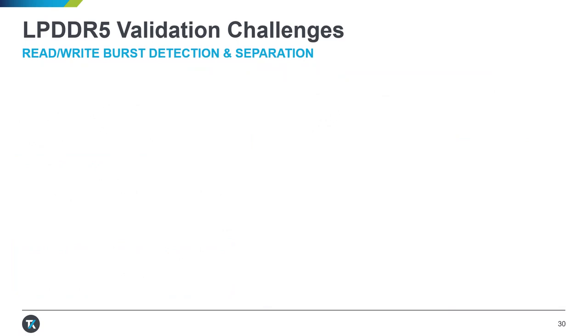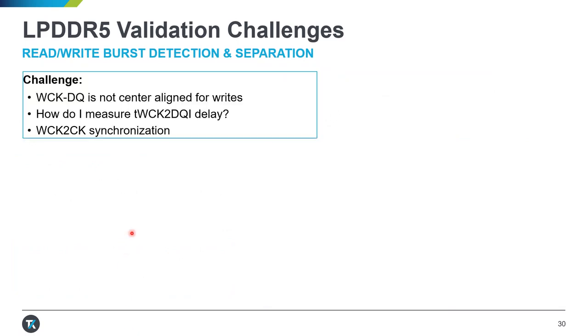Read-write bus separation problem. Similar to LPDDR4, writes are not center aligned. There is a fixed offset between WCK and DQ. However, having a dedicated strobe for reads and writes does make it a little bit easier to separate the reads and writes. But now we have to deal with WCK to CK synchronization.